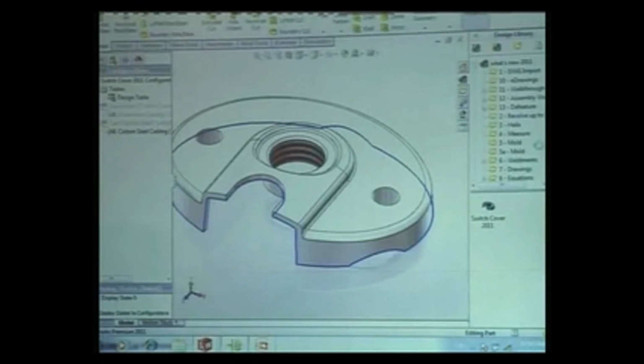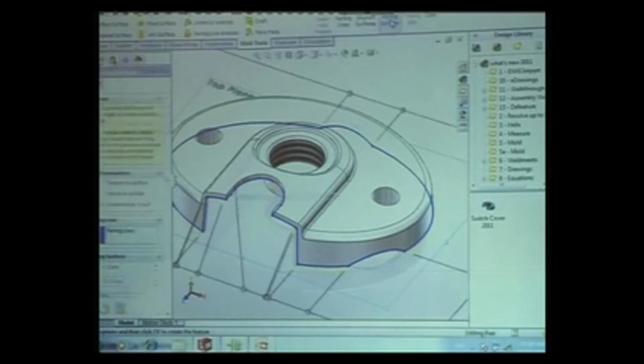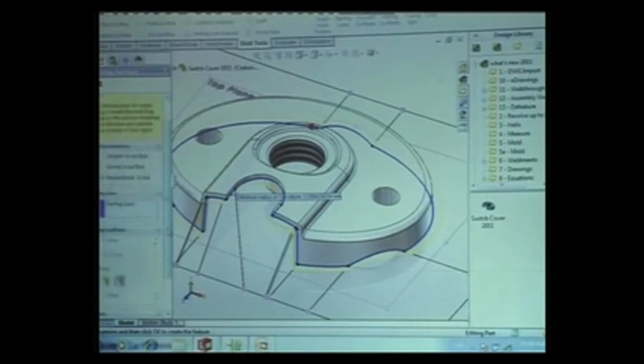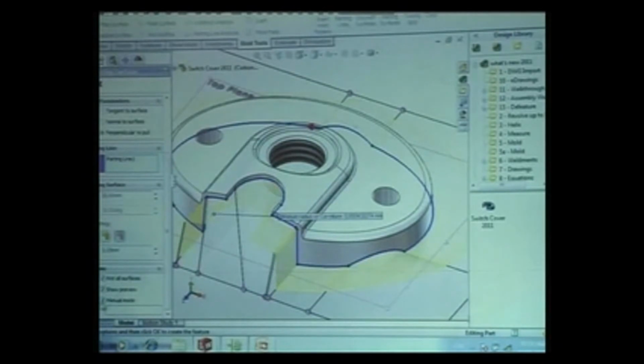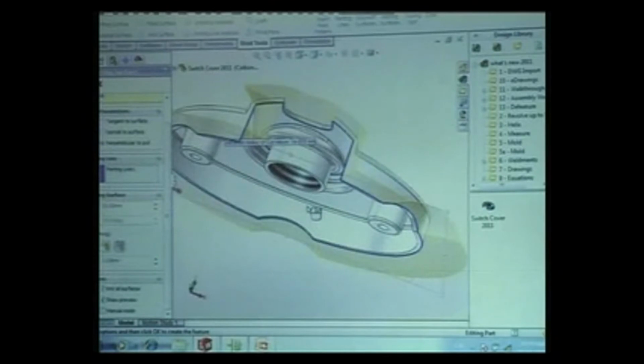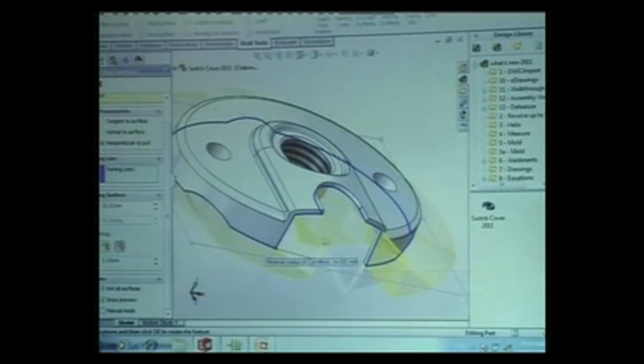Coming back to your question regarding the parting surface. Yes, that's right. Basically, in SolidWorks it is difficult to understand how exactly the parting surface should be directed. Let me take an example where I'll be creating a parting surface in an automatic way. You can see that inside SolidWorks we have got a gray tool, but there will be some overlapping of the parting surfaces here.